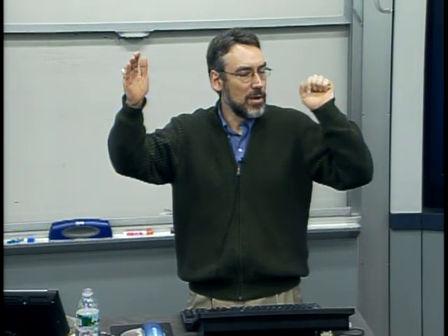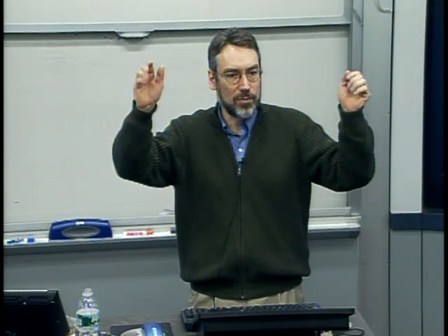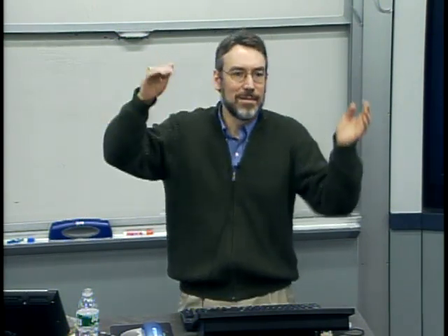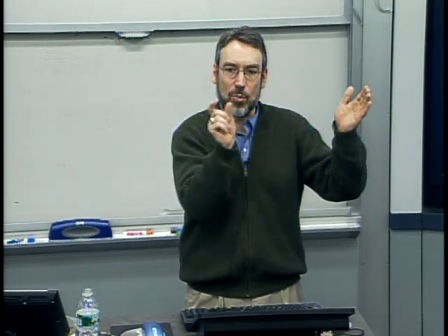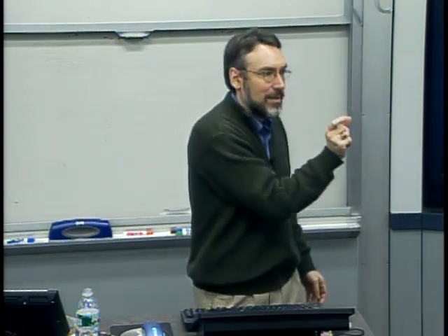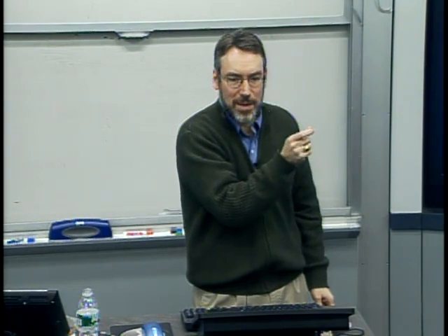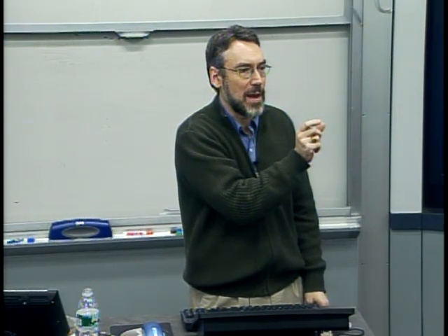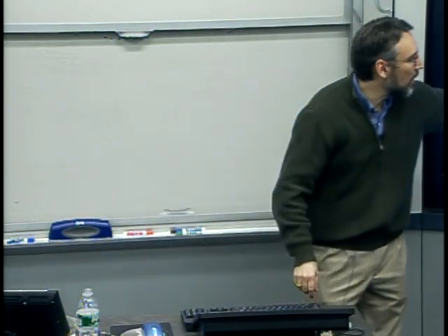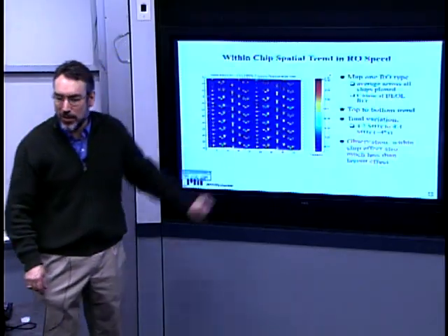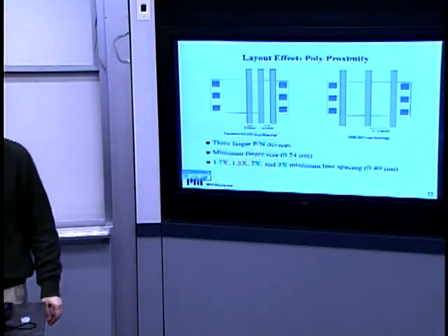If I were to say from center to edge, or from one edge of the wafer to the other, I have a systematic trend of about 10%, and I map that down to 1/10, because I've got 10 chips, that would be about a 1% variation you might expect because of wafer level sources on each chip. But what we find is something like 4%.